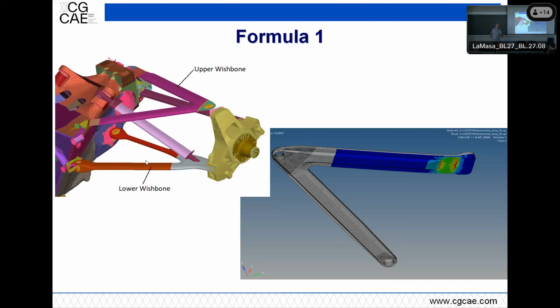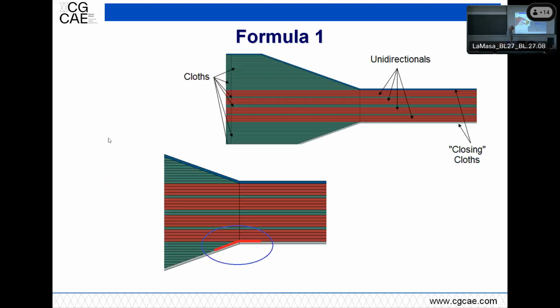So we were confident enough that the part calculated with the shell model would have survived. But actually it didn't. When it was placed on the test bench, just with up and down, plus some forces acting, simulating running load, the travel was from -70 to +50 or vice versa, so not really big, but not really small at all as well. And this was the philosophy of the construction, the actual one.